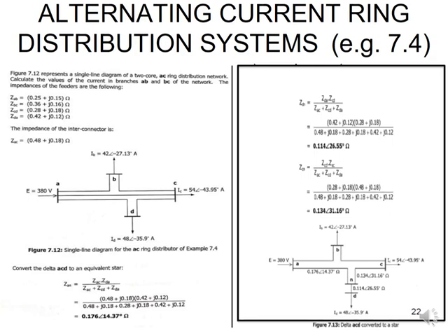So anyway, looking at converting the delta, which is ACD in this case, so it's your bottom one, to an equivalent star, you're going to have three impedances that you work out. Your first one being ZAN, and we already know how to do the conversion from delta to star. It's a multiple of the two, and you divide by the sum of the three impedances.